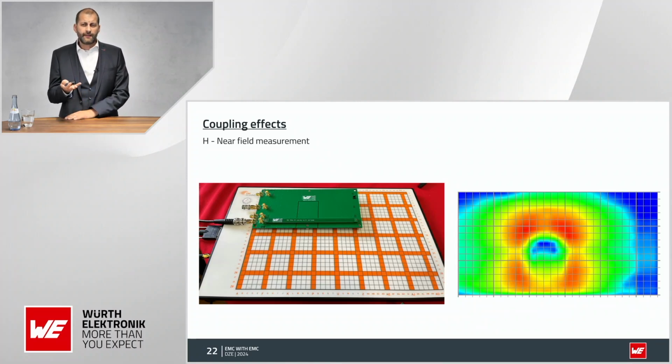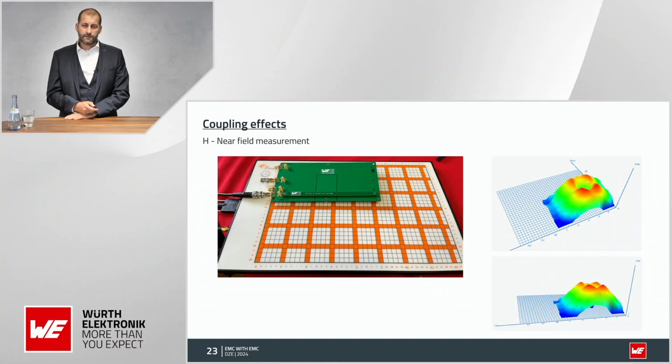But what do you see now? Well, you see something really nice when you change to the 3D view. You see we have no field in this area. Also nothing in that one. What happened? Well, here we have the transmission line directly over our ground plane. So the generated magnetic fields can cancel each other out. And they will, but only if we let them.